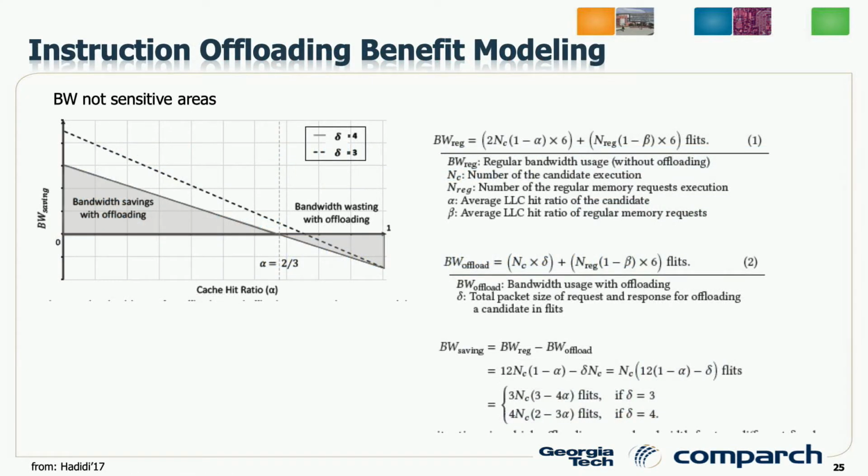So when you offload these computations, the key factor to consider is cache miss behavior. At a high level, if we bring data and then reuse it over and over in the processor, that means we get the benefit of using caches. But if we bring data from the memory, use it just once and then throw it away, then we don't get the benefit of the caches. So obviously, if we get cache benefits, then it's better to use the caches.